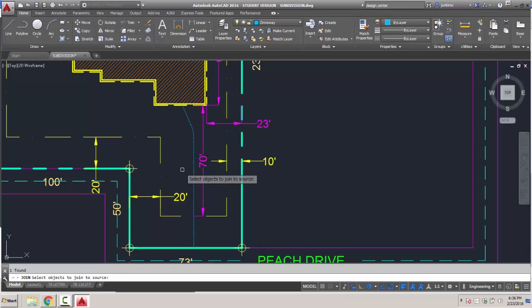And now we're going to do an offset. So this driveway's total width is 8 feet on both sides, so it's going to be a total of 16 feet wide. So we go to our offset tool right here, hit enter for through, left click here, I'm going to pull it over 8 feet, and here I'm going to pull it over 8 feet.